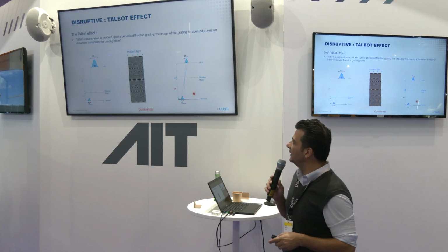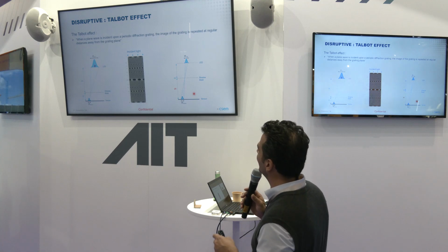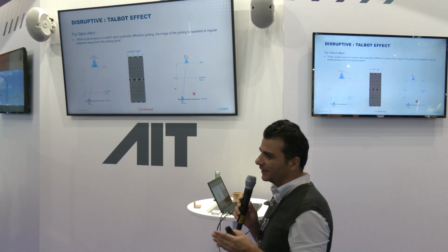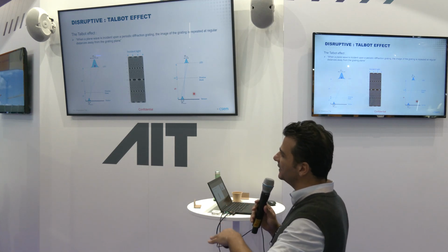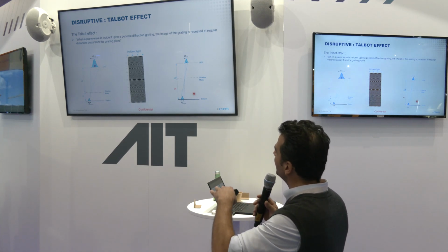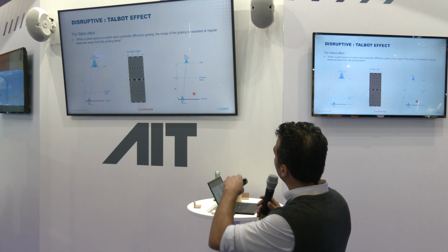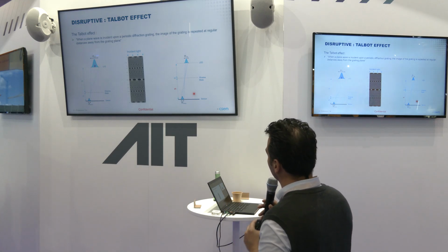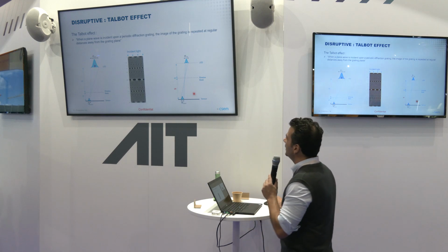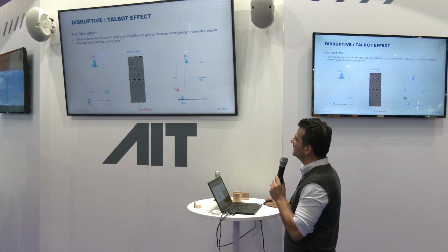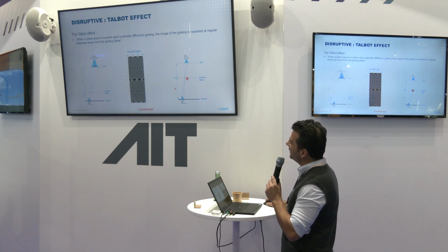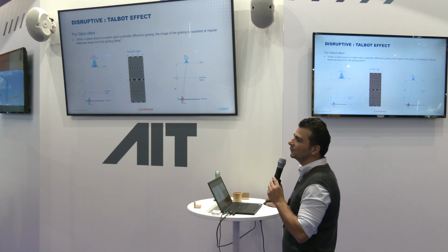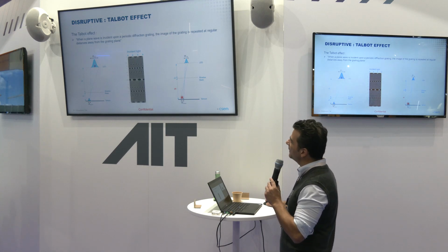And this is the novelty of our technology, the possibility that we leverage the Talbot effect. The Talbot effect is quite simple: if you have a plane wave incident on a repeated pattern, the diffraction will be periodic until we reach the point of the sensor. This allows me to increase the distance between my sensor and my shadow mask. Meaning now the error that I'm getting on my sensor, which is stuck at 10 nanometer, I'm able to decrease onto the object plane.